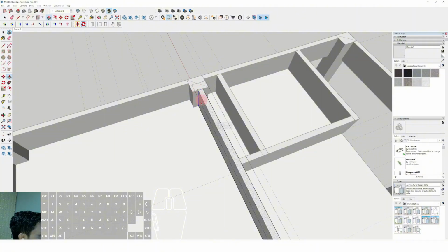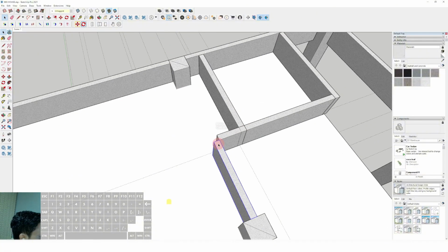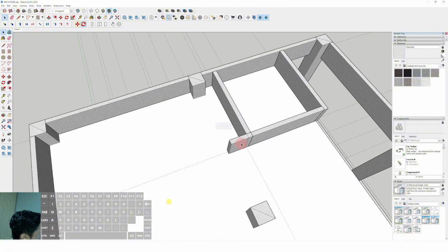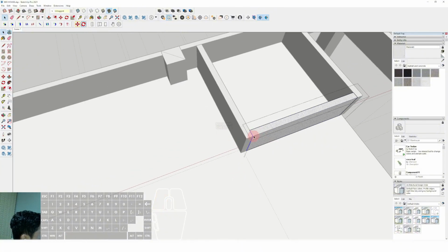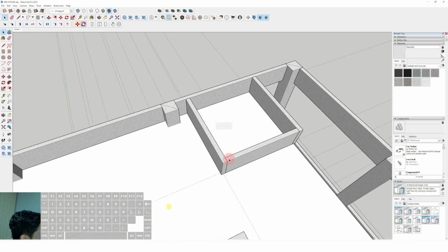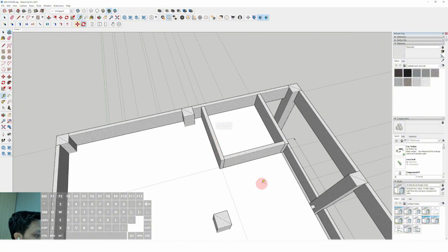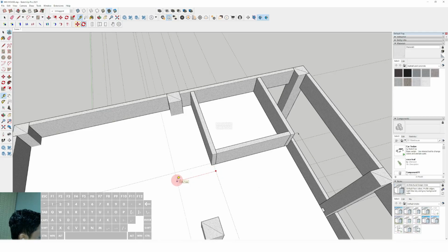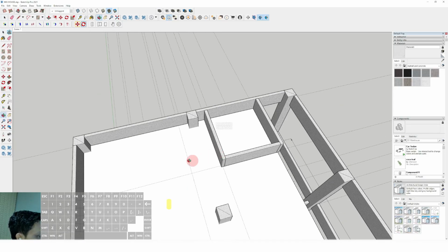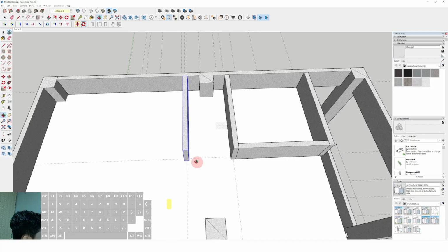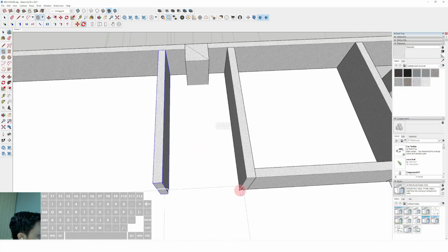We can cut this wall first. We can minimize this wall in here, or we can delete this one first. Okay, we can delete. We can adjust this angular connection. Okay, and then we can make the space in here 1.5 meter. We can click from this position to this position, 1.5 meter or 1500 millimeter. Then click this wall and select move, tab control, place to the position, and then we can make the rectangle and click this.